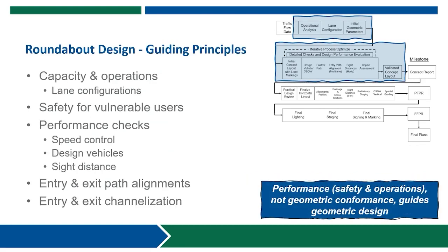The guiding principles for roundabout design: we want to keep these in mind as we work through the design of our single lane roundabout. Some of the decisions we make during design are also influenced by these guiding principles. Designers should strategically keep the performance objectives of safety and operations in mind and let them guide the selection of various design details. The overall design composition, how all of the approaches and the circle size fit together, and the resulting performance matters more than the individual dimensional elements.